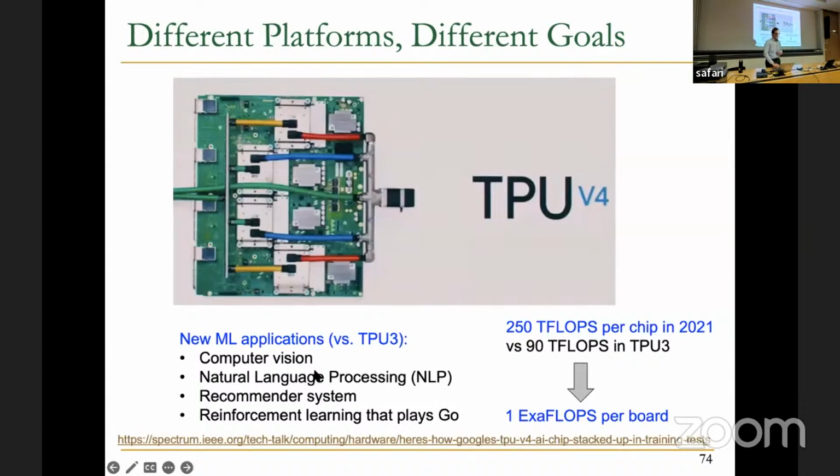Okay, this is a more recent specialized machine learning accelerator that you may have seen in DDCA. If you took DDCA, we covered systolic arrays. How many people know about systolic arrays? How many people don't know about systolic arrays? It's okay. Again, we may cover systolic arrays. It's basically a specialized acceleration mechanism to enable computation on the data you bring without writing the data back and forth too much to memory. The input data elements flow into a matrix, for example, and you do matrix multiplication, while reusing the data that's generated by the intermediate units.